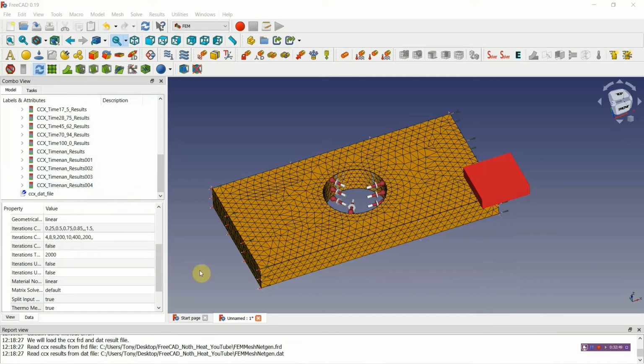I think the problem is that I haven't specified enough boundary conditions. At least that's the first thing I'm going to try. The constraints for X, Y, and Z are properly defined. The whole structure cannot rotate this way because of the constraints imposed here, but it can rotate this way around the X-axis because I haven't got a constraint here.